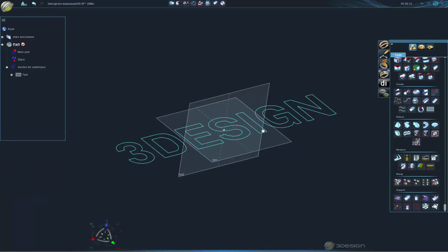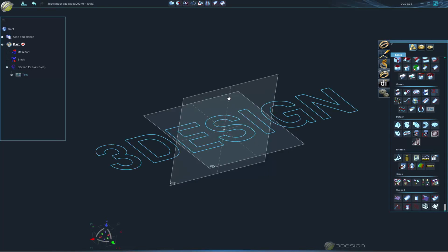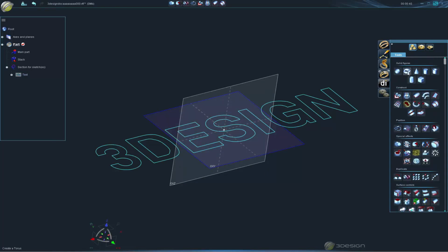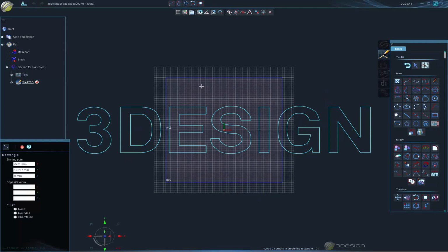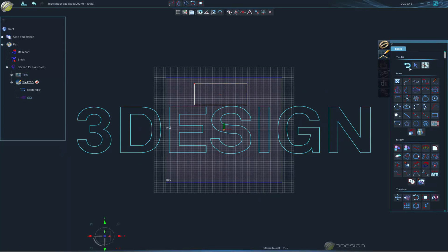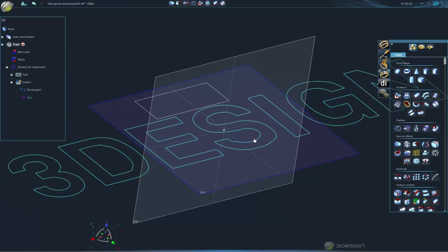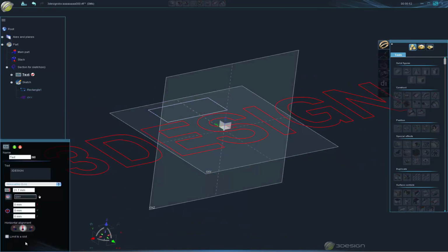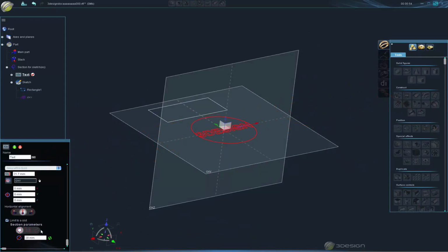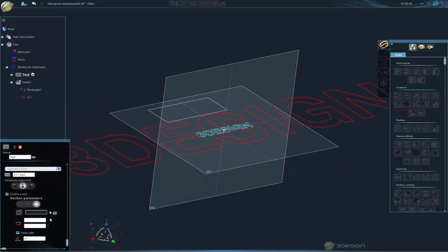The nice thing is that we can link this text to planes. We can link it to support objects, all kinds of fun stuff. The other thing we can do is link it to a slot. And what I mean by that is I'll just create an area, perhaps using a sketch. I can use objects as a slot, all kinds of things. So what I'll do is in my text, limit it to a slot, and I can draw a shape, or I can use my custom shape.